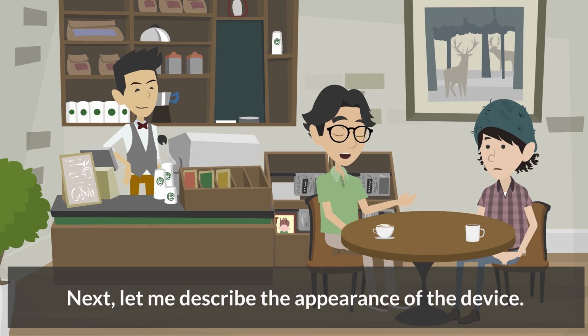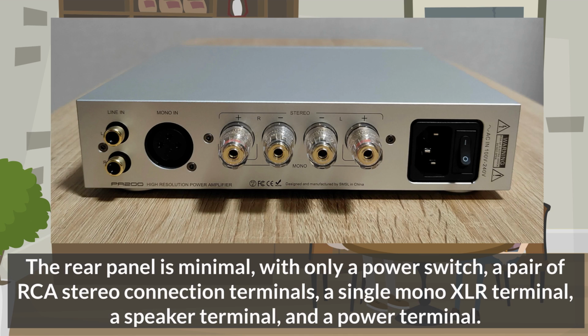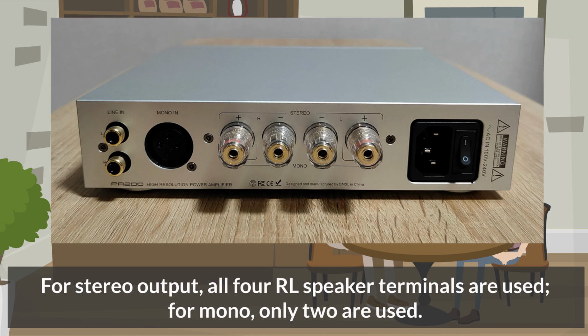Next, let me describe the appearance of the device. The front panel just has the volume. The display is simple, showing only the volume value. The rear panel is minimal, with only a power switch, a pair of RCA stereo connection terminals, a single mono XLR terminal, a speaker terminal, and a power terminal. For stereo output, all 4 RL speaker terminals are used. For mono, only 2 are used.